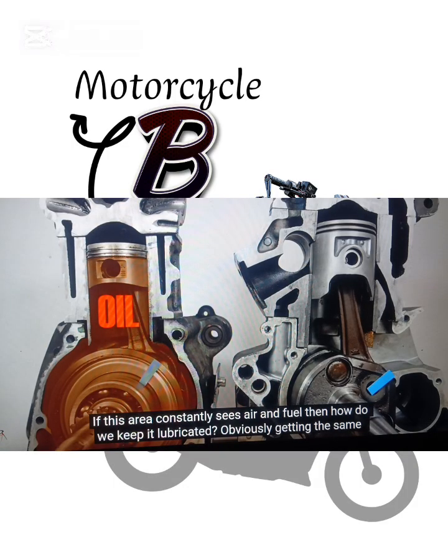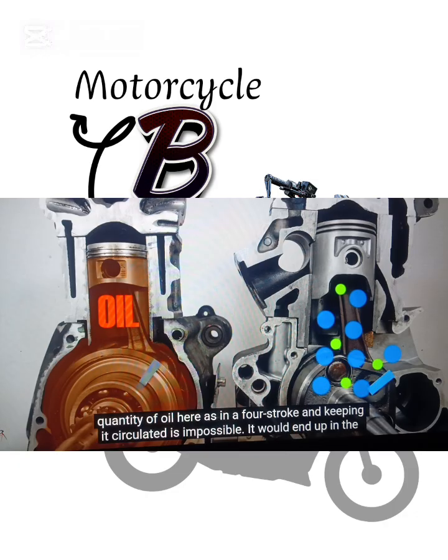If this area constantly sees air and fuel, then how do we keep it lubricated? Obviously, getting the same quantity of oil here as in a four-stroke and keeping it circulated is impossible. It would end up in the combustion chamber and probably prevent combustion from ever occurring. We also know that fuel is a solvent, making things even more difficult for the rotating assembly of the two-stroke. So then, how do we prevent metal-to-metal contact in the two-stroke? Well, the answer is a compromise.